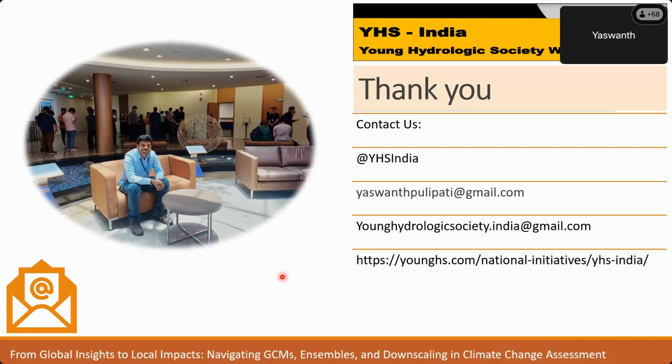So use at least 30 years of data for calibration and keep 5 years for validation. Many gridded data sets have been developed in the last 2-3 years across the globe, so there is an ample amount of data available.